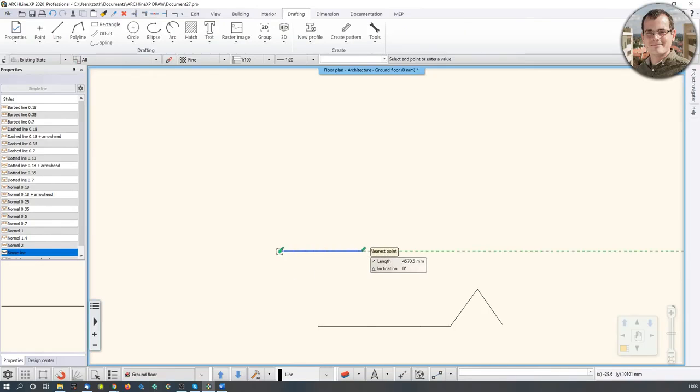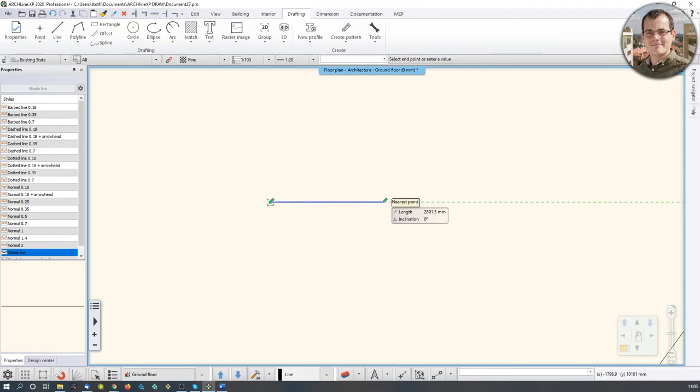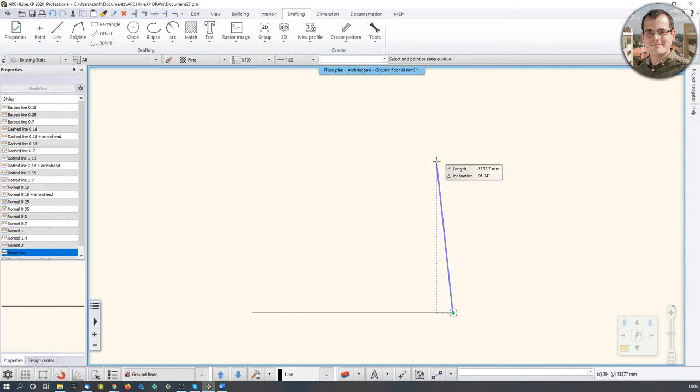Okay, let's make an exercise over here. I want to create a rectangle, which is, let's say, 5,000 millimeters in every direction. What I do is I start to pull my cursor like this, and instead of trying to find the 5,000 mark with my cursor, which is impossible, I'm just going to type in the value, 5,000. There you go. And then what do I do? I move my cursor, and if I do it vertically, then the software would snap my cursor to a vertical axis, and then I can just type in the value again, 5,000.